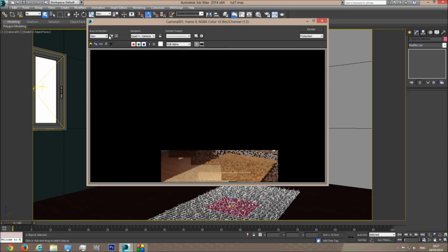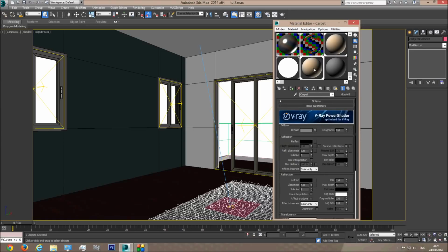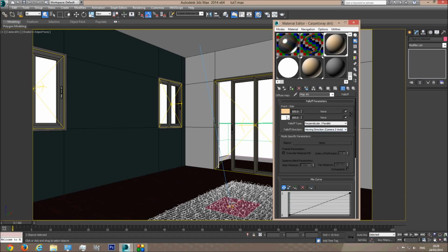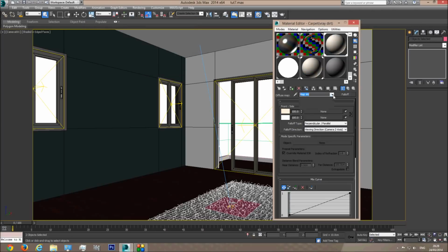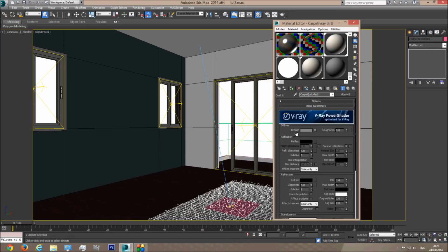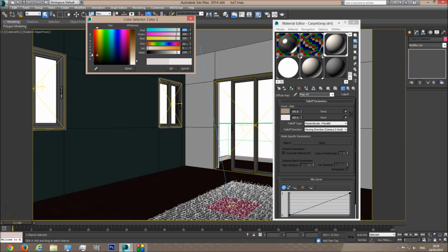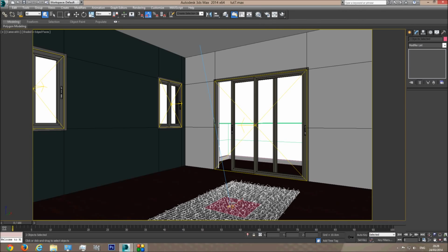Now let's render the whole image and see how the room looks with our carpet. You know what? Let's make the carpet a little bit brighter. The basic carpet material, a little bit brighter here. So this is on full white, and let's take this down almost to full white, something like this. And the occluded part we will make just a little less dark, like this and here. Alright. Now let's try rendering the room.